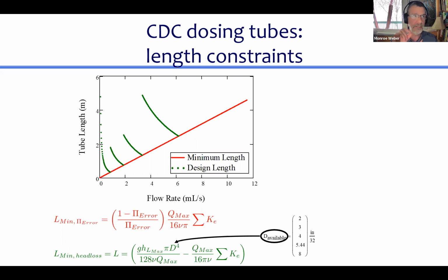So if we increase the height of that, that's more head loss through the plant, a bigger elevation change across the plant. And that essentially means that the building that the plant is in needs to be taller, because all of the difference in elevation and water in the plant has to be accommodated inside the building. And so if you increase the difference in water between the low end of the plant and the high end of the plant, the building needs to get taller to accommodate that extra height. So it actually costs you money every time you add more head loss to the plant.